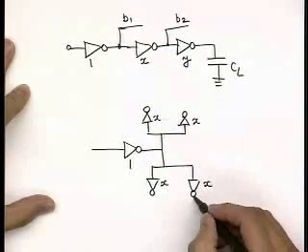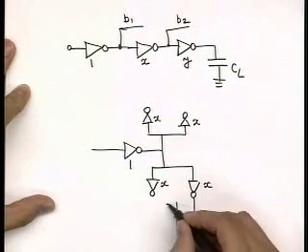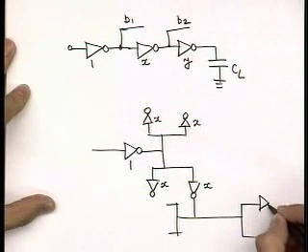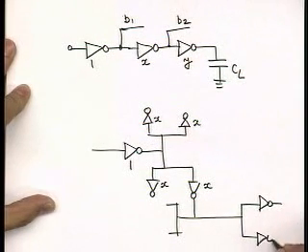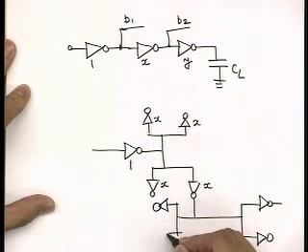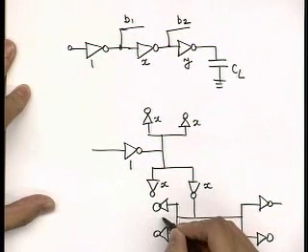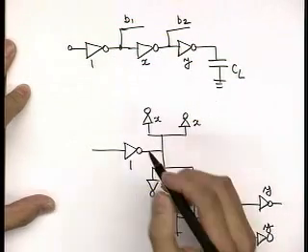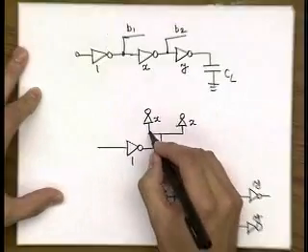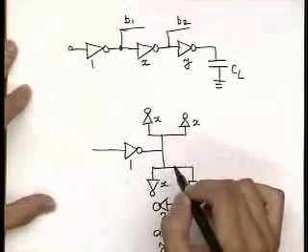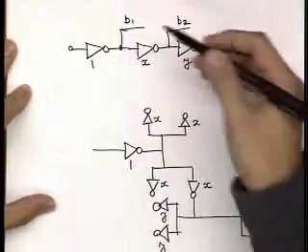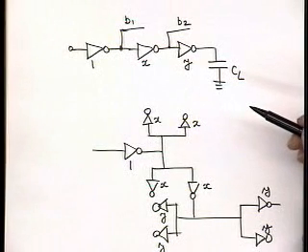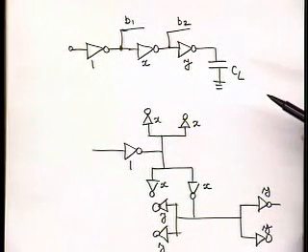And then you further distribute each of these to your clock subdomains, and the size of each of these is y. This factor that represents the number of these parallel branches is what we call the branching factor. And we will come to that on Tuesday when we explain logical effort and introduce these concepts.